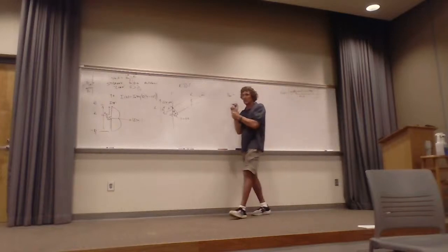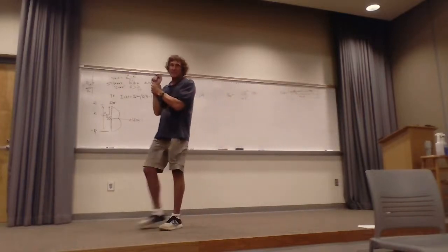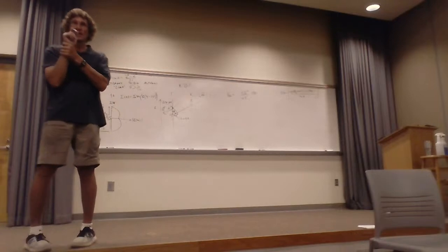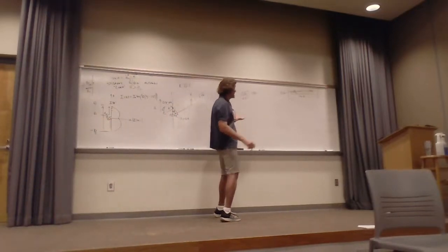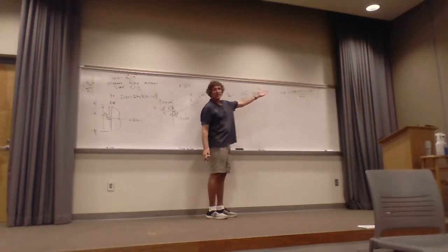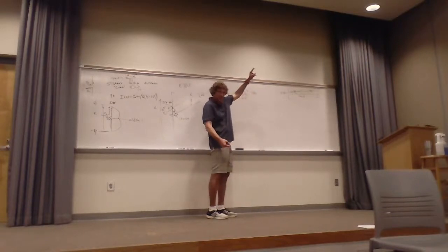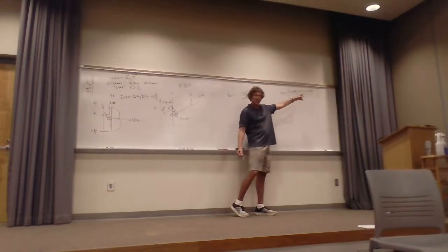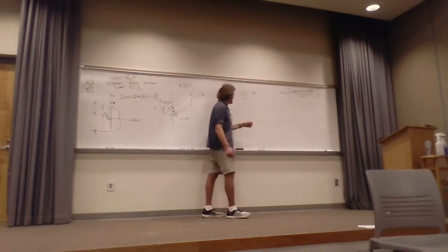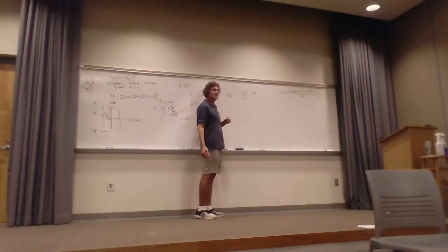You take a look in his book. I'm glad you guys have your books. What's nice about this is, if I've got this, I know the length of the antenna. It could be a wavelength long, half wavelength, 3/4 wavelength, doesn't matter what it is. Now you know the angular variation. And I can get the average power density right there by taking that thing and squaring it.